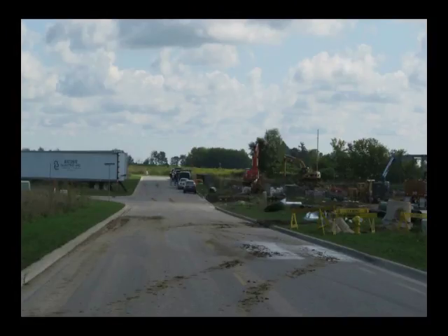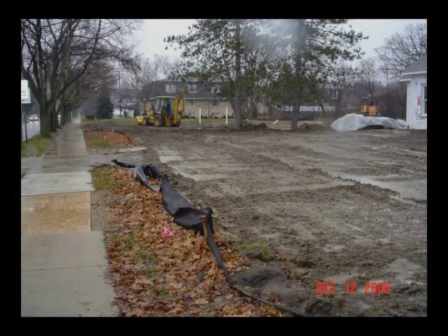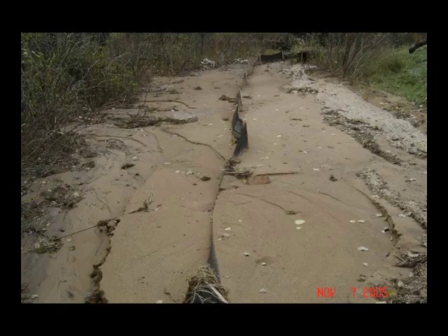Inspections following precipitation events should be performed with the idea that some measures may need maintenance or replacement after the event. These inspections will allow you to see the drainage pattern on site. This makes it a good time to look for areas that need protection that were not expected in the planning stage. The logs or inspection reports should reflect everything found during the inspection.